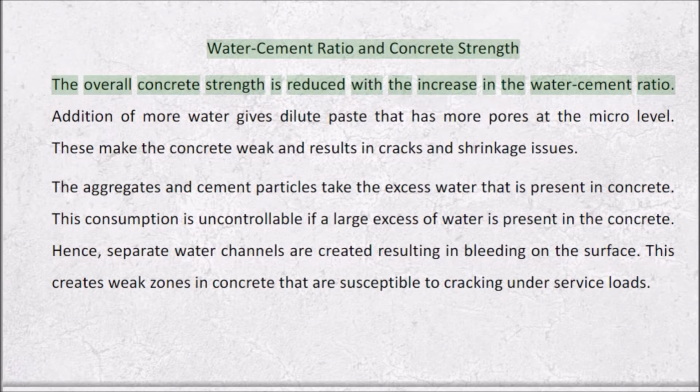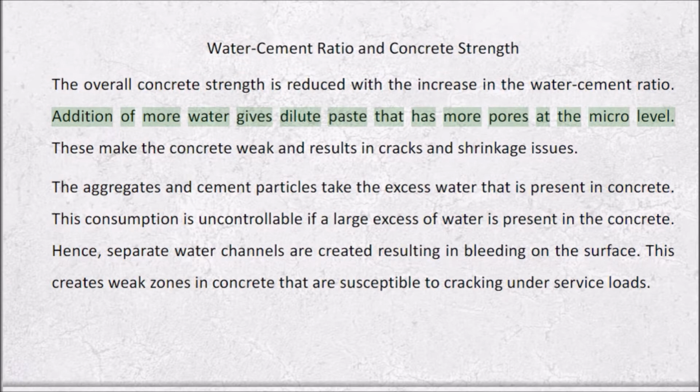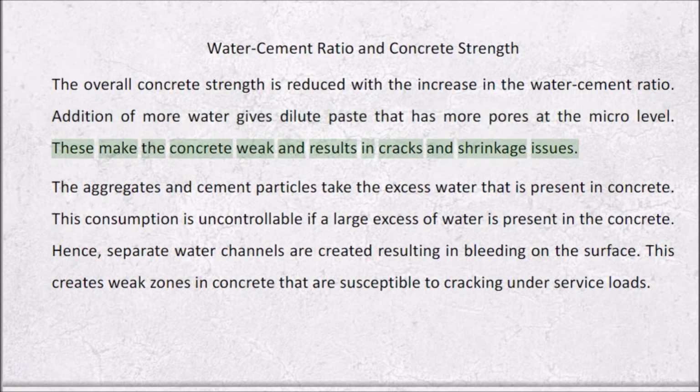Water-cement ratio and concrete strength. The overall concrete strength is reduced with the increase in the water-cement ratio. Addition of more water gives dilute paste that has more pores at the micro level. These make the concrete weak and result in cracks and shrinkage issues.